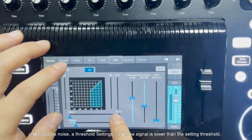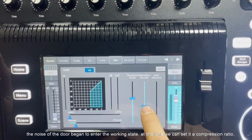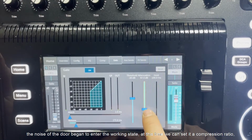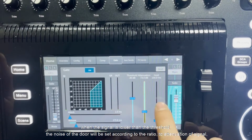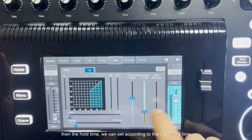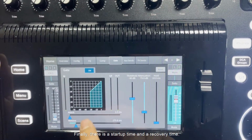Next is the noise gate and threshold settings. When the signal is lower than the set threshold, the noise gate begins to enter the working state. At this time we can set a compression ratio. When the signal is lower than the threshold, the noise gate will attenuate the signal according to the ratio. Then the hold time we can set according to use. Finally, there is an attack time and a recovery time.